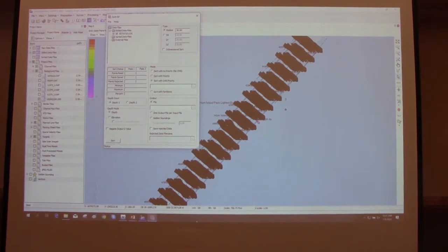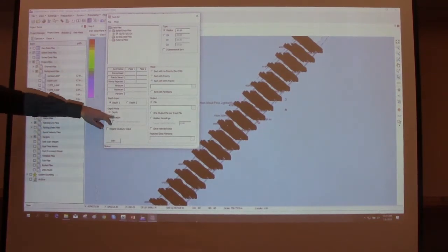If you're editing data with a negative z-axis, it's making the assumption that in HYPACK negative is going up, so it's actually going to save your deepest value. And I've been on a job years ago where the contractor and the other company, their volumes weren't matching, and it turned out the contractor was inverting their data to elevations and then sorting it. So there was a good half a foot difference between the two data sets. We were able to sort that out. So that's when we actually put this option in to work in depth or elevation data.